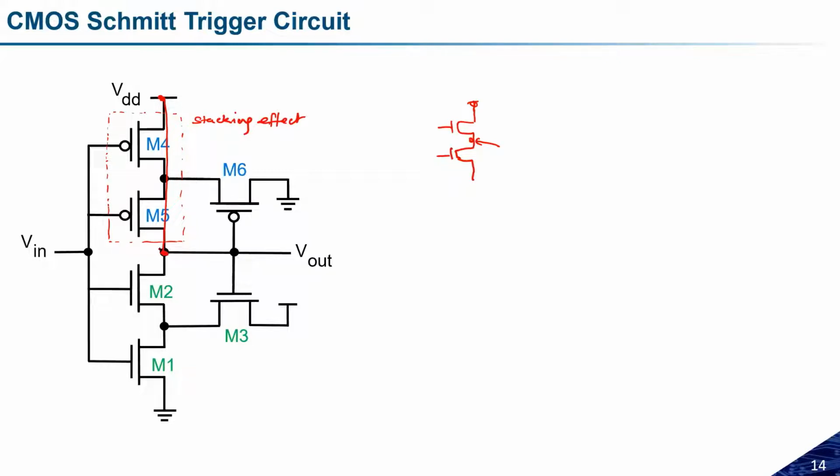I'm just leaving it here because I may offer one more course on low power circuit design in the next semester, so you can opt for that one and then you will understand this concept. For now, just understand that we have already studied stacking and the effect of body bias on this node, which changes the effective body voltage VBS of the transistor. That leads to reduced leakage current, or a threshold voltage change, something like that.